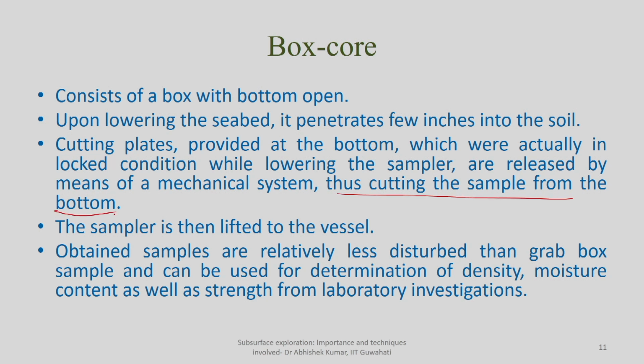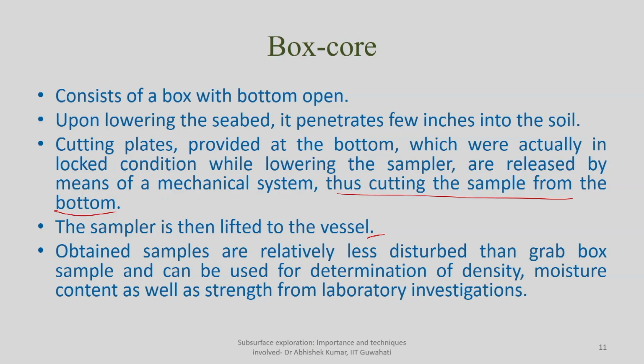So, you lowered the sampler which was open. As you lowered it, it must penetrate a certain depth, and once it has penetrated, by means of a mechanical arrangement, a cutting plate will come, which will disconnect the contact between the sample within the sampler and the actual seabed material, and contain it inside. Then you can shift it or bring it onto the surface, onto the vessel, from where you can go for detailed laboratory investigation.